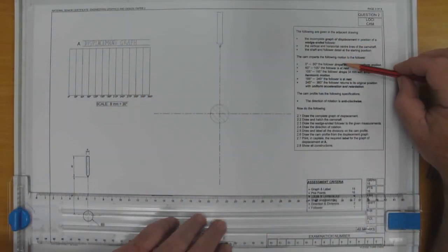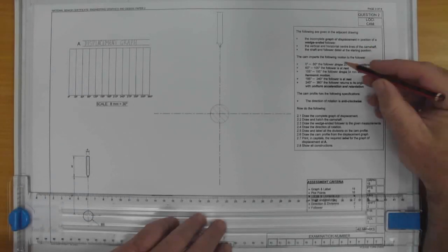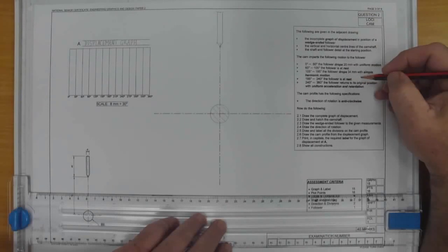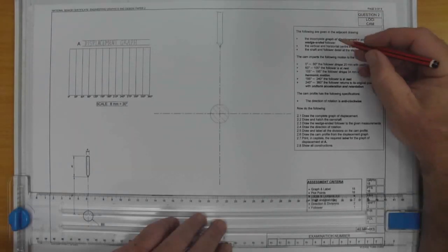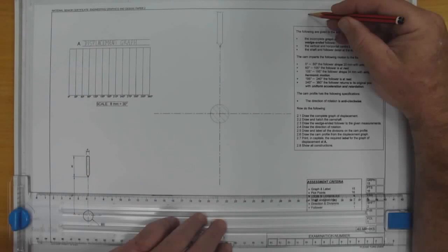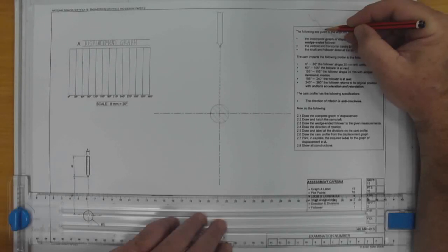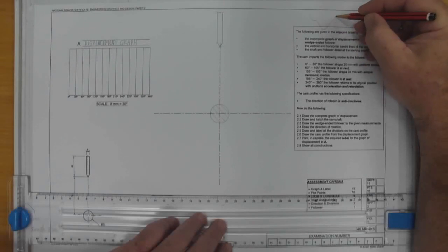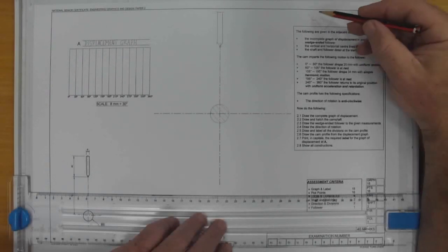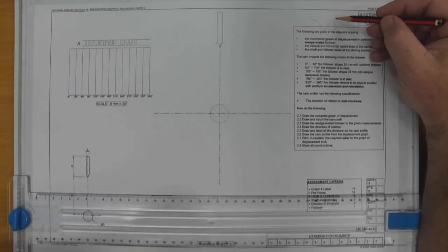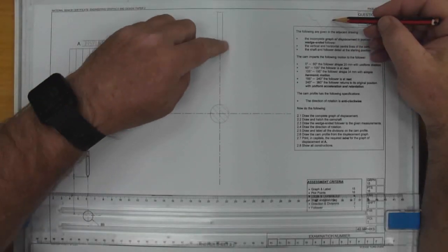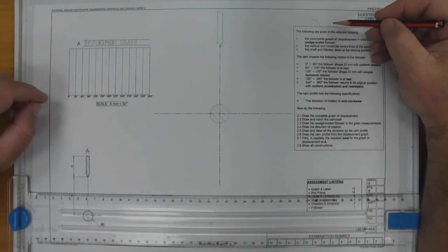So if we went through the information here, it's telling us that from 0 to 60, and again what you could do is draw a little bit of a small point here. So it says here from 0 to 60, it drops 20, then it's at rest, then it drops 34, then it's at rest, and then returns to its original position. Okay, so that's given me a bit of an idea of what it's going to look like, which makes sense about why this follower is so high.